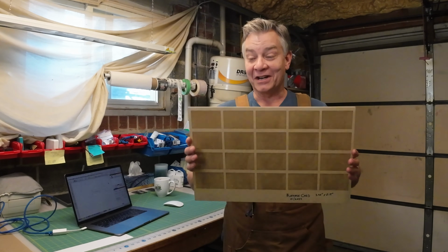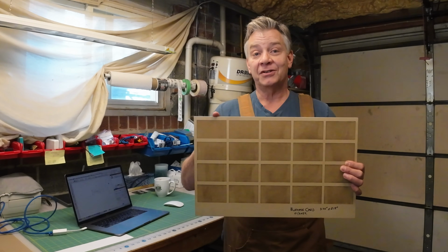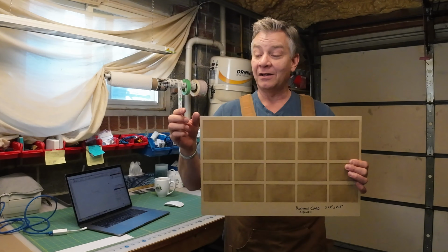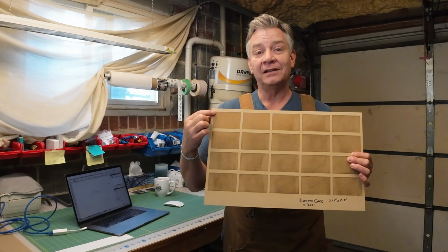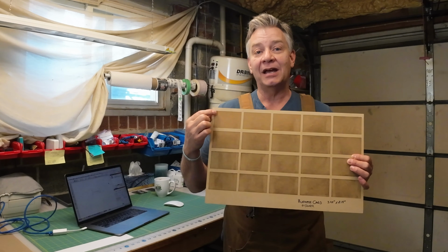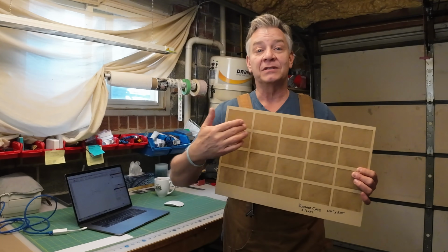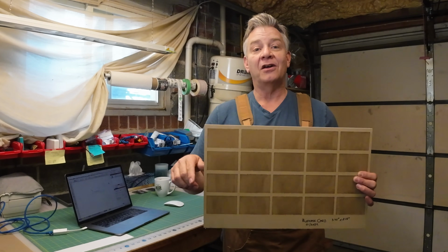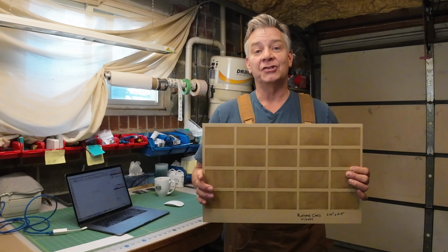Up until yesterday, when I realized why it's so helpful, every time I was burning production cards, whether they're for myself or someone else, I'd put my template in, and then I would play with the laser, trying to get the laser target dot to exactly line up in one spot. Then I'd frame it several times to make sure it was in the right workspace. I'd do my autofocus, set my origin, most importantly, and then start the job. Well, now I don't have to do that anymore. Let's take a look at the difference for absolute origin.